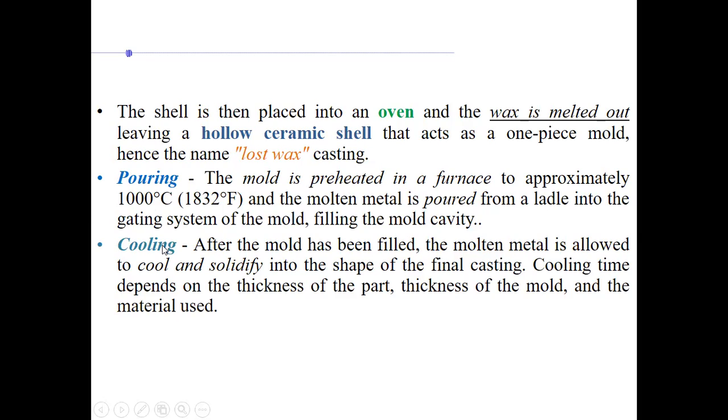Cooling, right? Once it is solidified and cool, you see, it depends on the thickness of the part. How much cooling time is to be given depends on the thickness of the mold and the material used, because the solidification time will depend on the material, thermal conductivity, etc. So that will decide the cooling time.